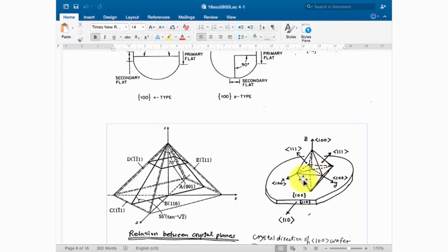Okay. So when we do etching on this silicon substrate, the final structure will stop at these four surfaces underneath. The slowest surface is the 111 surface. When you look down at the surface and do etching, no matter how long you go, finally they will stop at these four surfaces. These four surfaces are 111 surfaces, the slowest surfaces for etching. It just stops over there. So no matter what kind of structure you put on top, finally you will get a pyramid structure underneath if you etch long enough. All the structures will stop at the 111 surface.